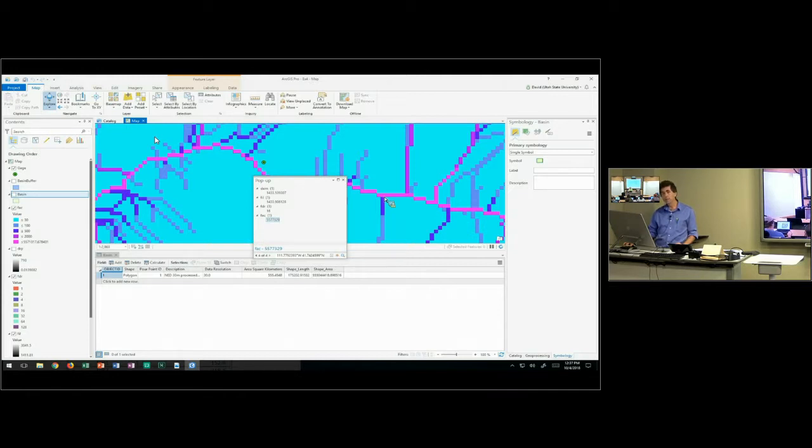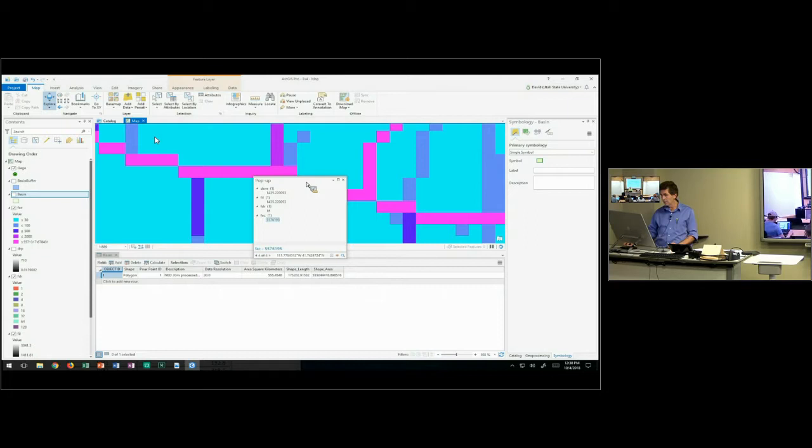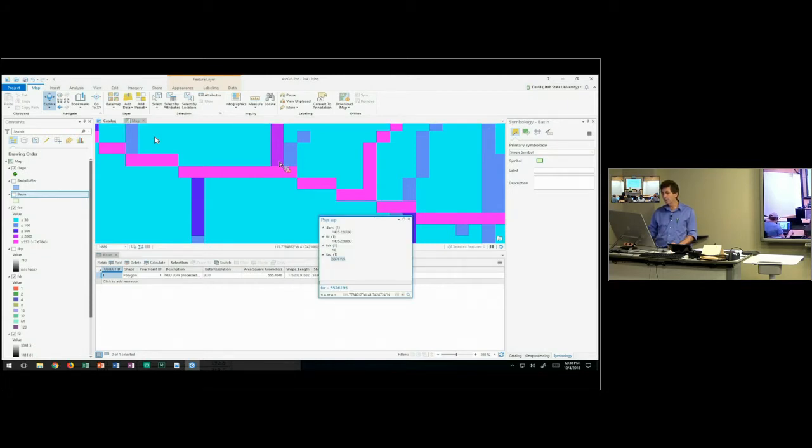there's 899, nearly 900 grid cells flowing in. There's a value there, 7,098, and there it's 7,111. There it's 6,195. So we would infer from those numbers that we just looked at, well, what would we infer? Does this grid cell go diagonally into the stream or straight down into the stream? Depends on the flow. Does anybody remember the numbers?